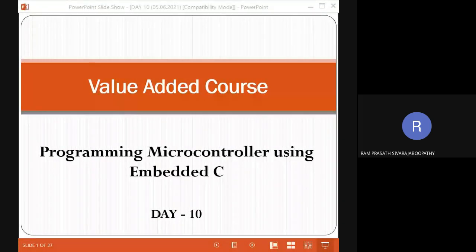It is the universal protocol used in the automobile's controller area network. There will be many controllers controlling the individual aspects of your automobile. Your automobile has many control units, many microcontrollers, all connected together using the CAN protocol. That means a microcontroller gets some information from a sensor and shares it with all the devices. Whichever device needs it will consider the message, otherwise it will discard it. But only one message can be broadcast at a time in the CAN protocol.